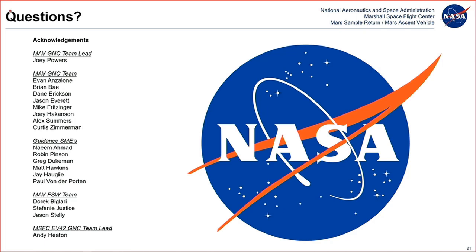So I apologize if I misspoke. Avionics are absolutely on the first stage. The second stage has a very simple time sequencer that we can just send time-based events from separation. And the second stage is spin stabilized, right? Passive, kind of. That's correct. Letting physics do the work for us.